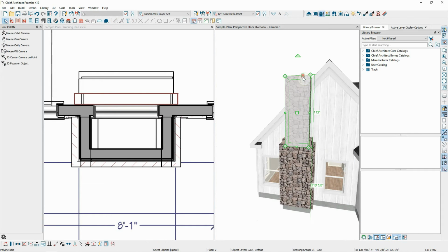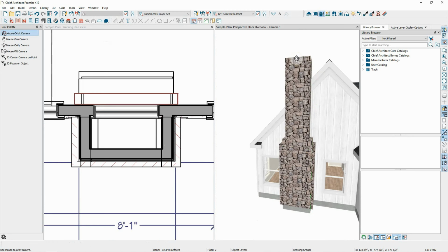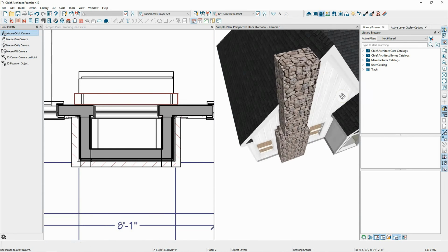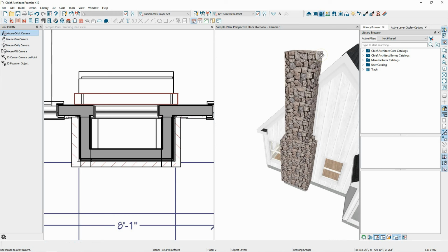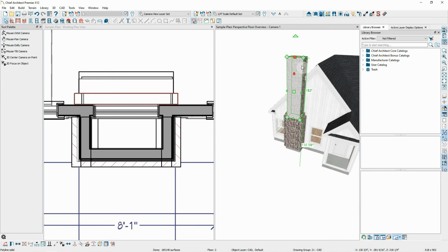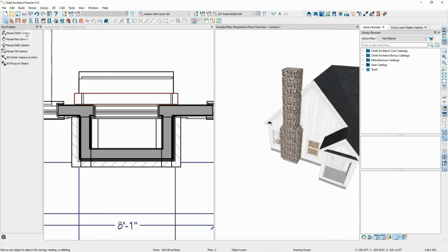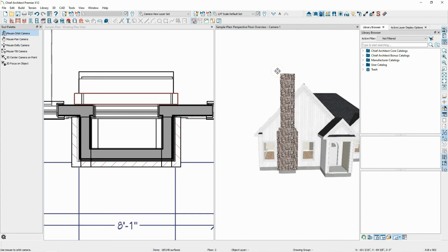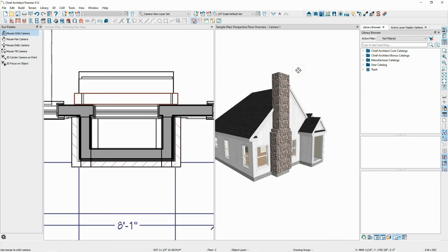And I probably need to pull this chimney up a little bit more. Remember, you have to be 2 feet above anything within 10 feet of your chimney. So you're going to want to get into elevation and get all those measurements and make sure that this is 2 feet above probably this peak here. So you'd want to get into elevation and check all those dimensions, but we'll get into that in a minute.